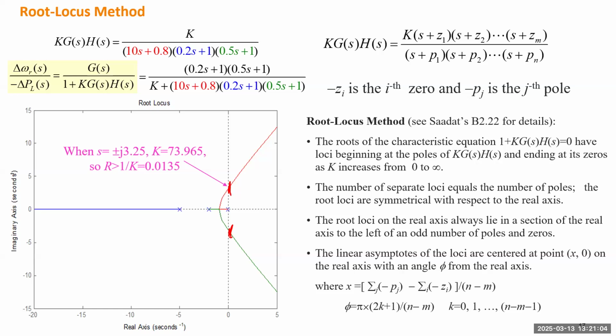And this one cannot be root locus. And the one in the middle of the next two has to be, because on the right-hand side of that locus, there's only just one. And this one cannot be, because on the right-hand side, there's a zero. So the first step is you identify those poles on the plane or on the axis, and then you try to decide which section belongs part of the root locus.